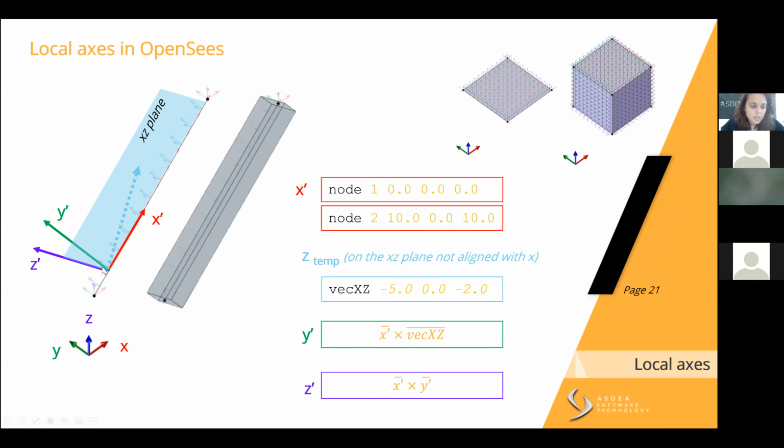So let's say that this is your zero length and it's not a beam column like here. When you want to say how this system has to move from local to global, you define a vector that is in your hypothetical x-y plane, because with the x-axis you're just saying what's the directionality of the first characteristic axis, but you're not saying how the section of the hypothetical element will have to adjust around that axis. Because you could be oriented in any of the directions.